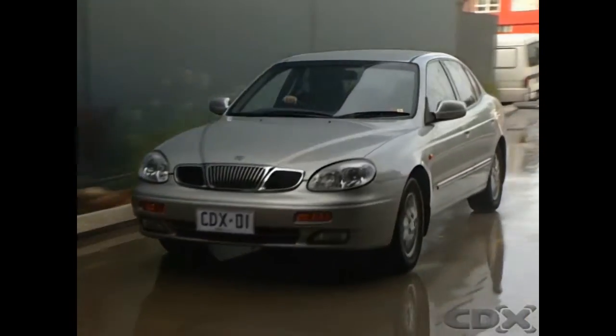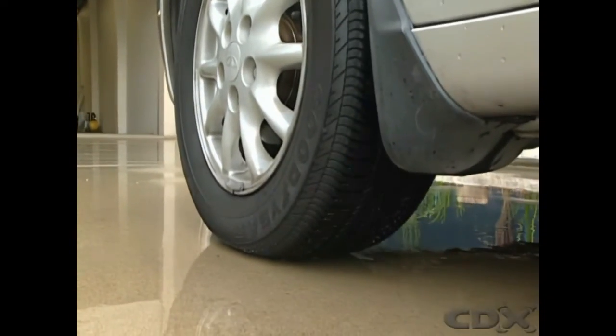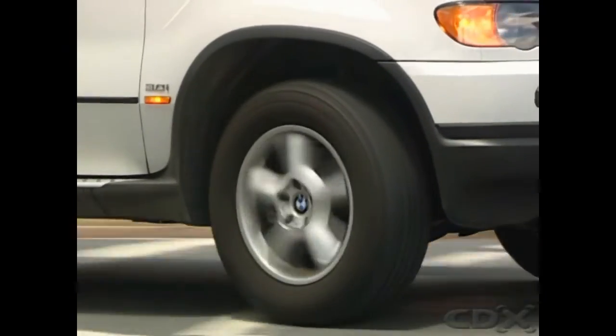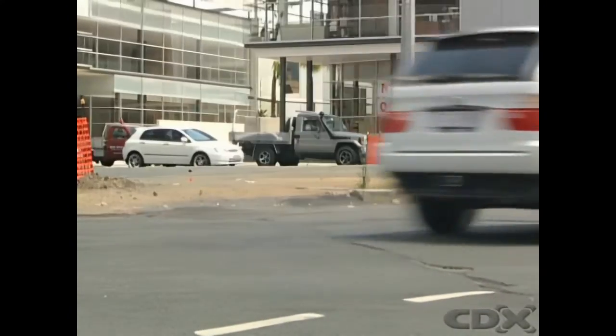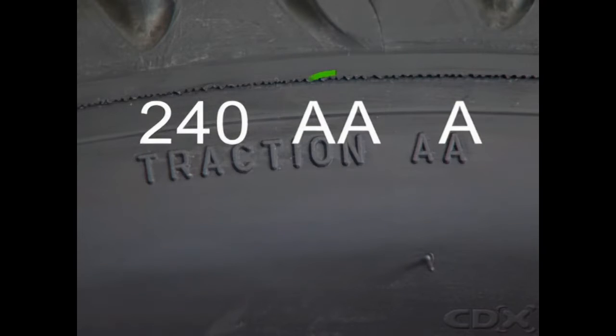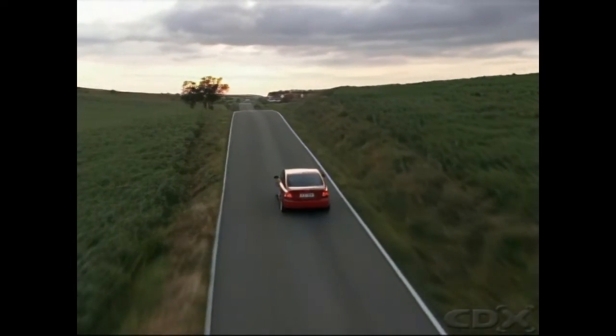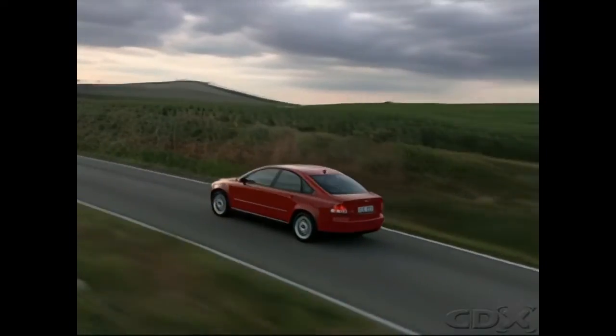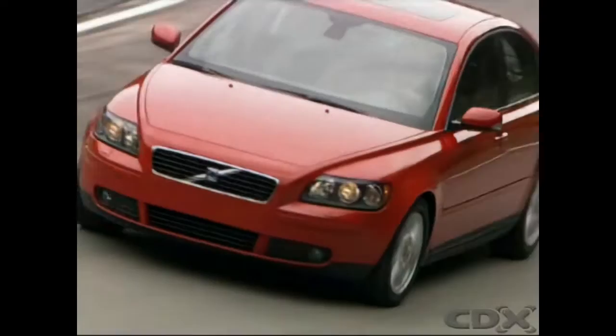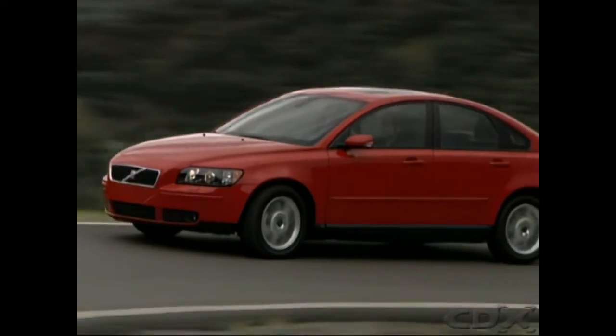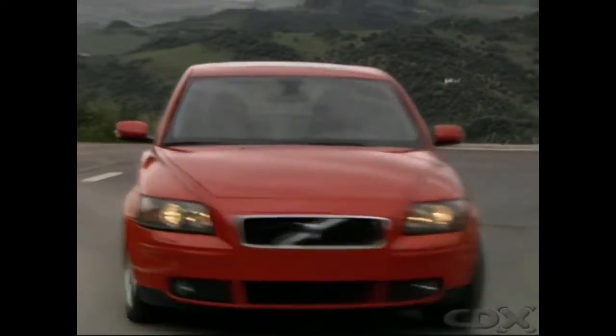The rating is based on the tire's ability to stop a vehicle on wet concrete and asphalt in a straight-line situation. It does not indicate the tire's cornering ability. The tire traction indicators are rated as AA, A, B, or C. AA is the highest rating. It is important to note that the test and relevant rating does not indicate hydroplaning resistance, dry or snow traction capacity, or cornering capability in wet, dry, or snow conditions.